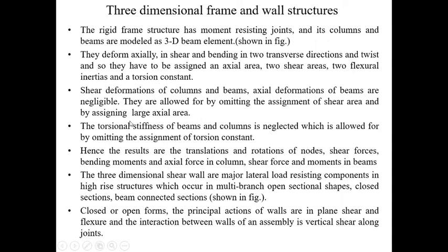Then the torsional stiffness: the torsional stiffness of the beams and the columns will be neglected, which is allowed for by omitting the assignment of the torsion constant.